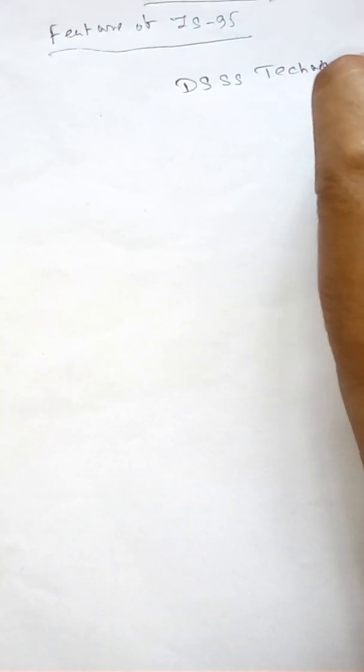This technique is used, and IS-95 uses a speech encoder, Qualcomm 9600 bits per second code excited linear predictive coder, QCELP, which can detect voice activity and also reduce the data rate up to 1200 bits per second in silent periods. Then, it uses specific modulation and spread spectrum technique in its forward as well as reverse link. It is compatible with the IS-41 networking standard.